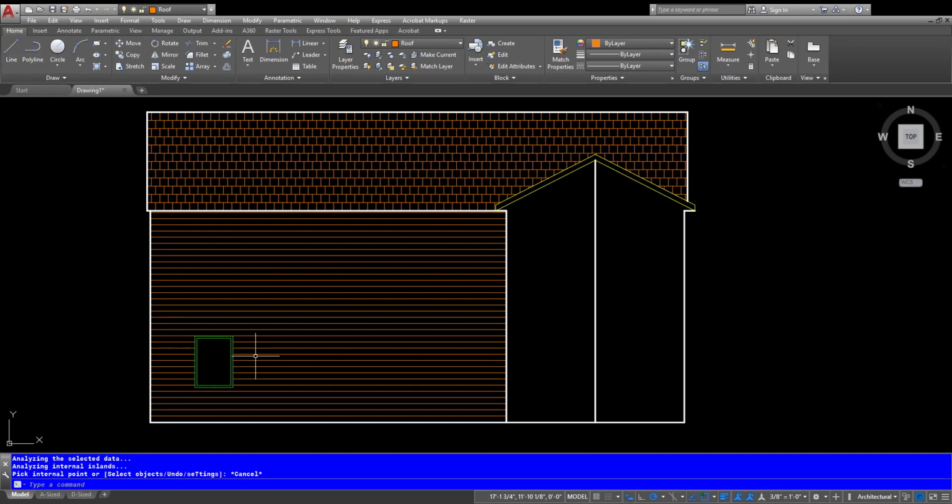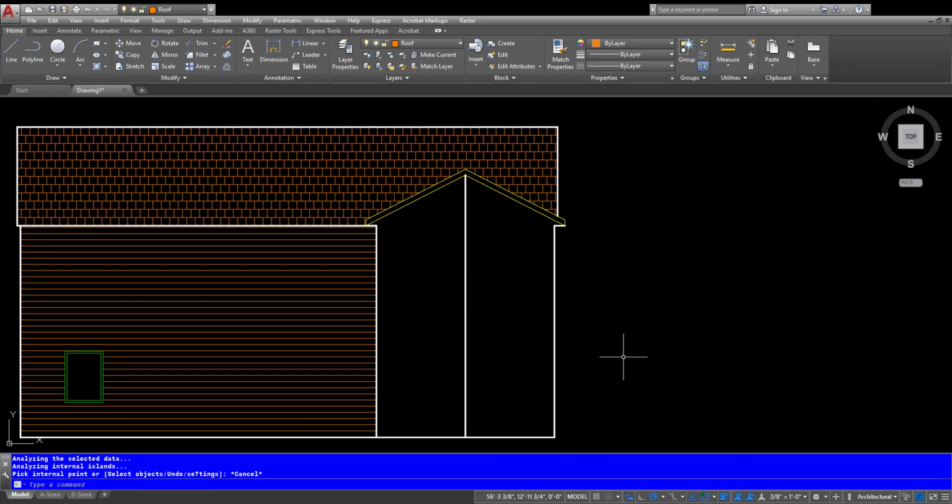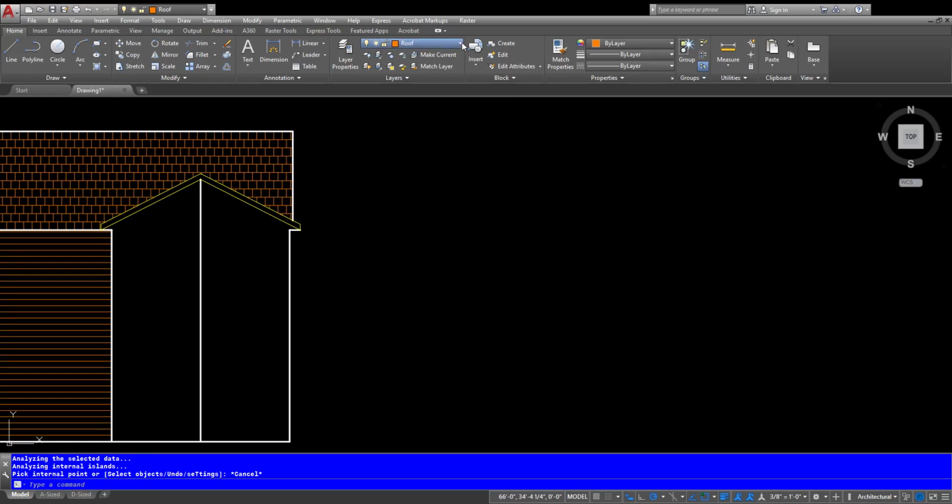So if I continue on with this right now, which I will do, I'm going to show you guys how to do one more item, and that is the chimney. Not the chimney, but rather the fan light detail. The fan light is actually pretty straightforward. We'll just go to the Windows layer, and you're going to draw a line 3 feet, because that's what it shows there. So make it 3 feet.